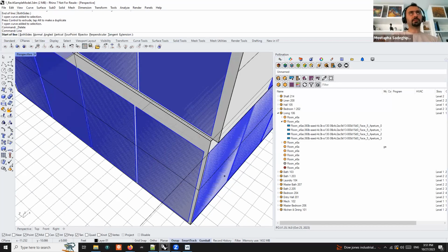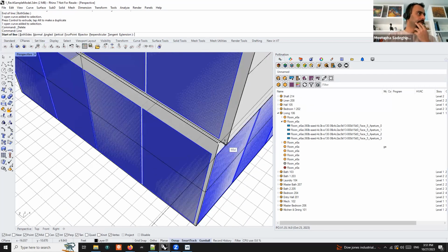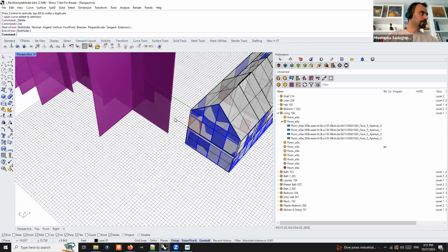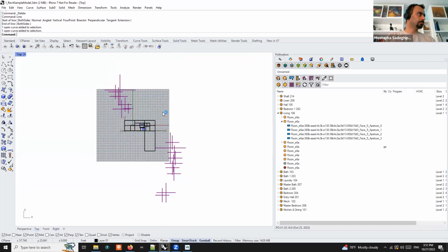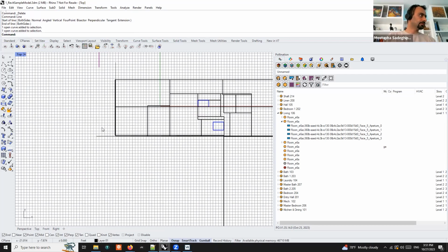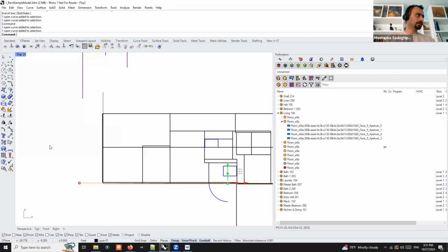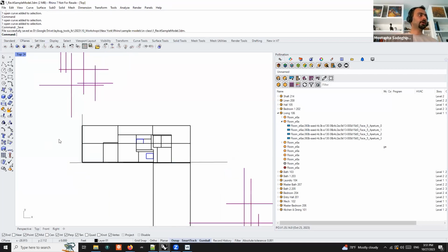All that really matters is how it looks in plan. I can do it like this, hold down shift, it should be fine. So if I go to plan view or top view, you can see these two lines, right? I press F7, so I don't see that. So this is one line and this is another line. Why do I draw these lines? Because similar to PO align in elevation, we have a command for PO align in plan, right?